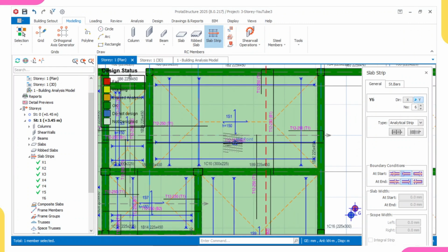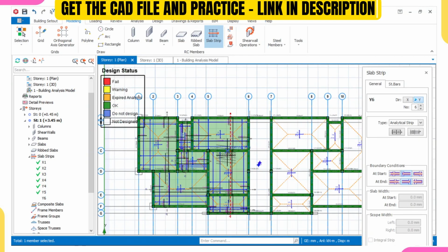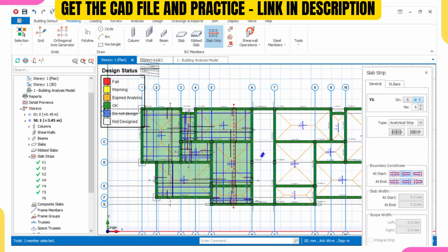In fact, I'll just advise you generally, once you come to slab, make sure that the minimum spacing that you use in slab, that's my advice, just use 200. That should be your minimum spacing once it comes to slab. So with this now, I believe that we have come to the end of this video.